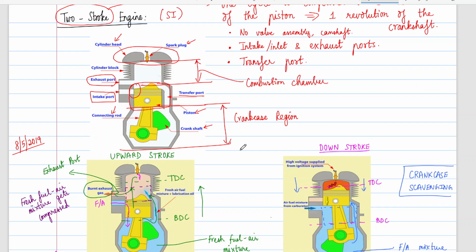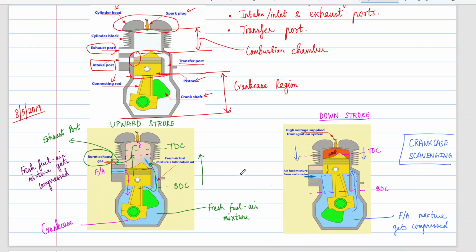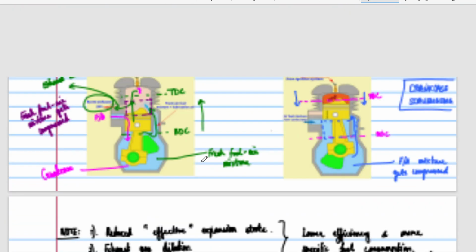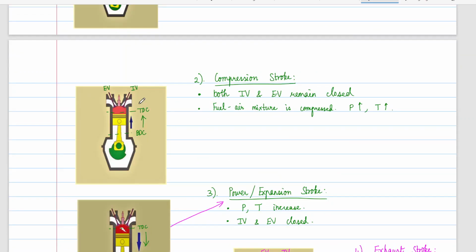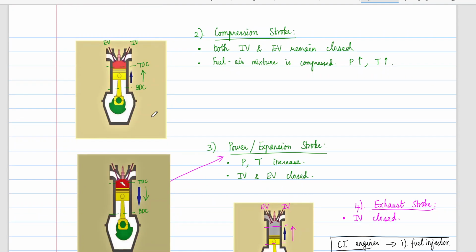are allowing you to directly, instead of sending in the fuel air mixture, as in the four-stroke engine here, where we are introducing the fuel air mixture, instead just introduce the air and directly inject the fuel. It can be diesel, or it can be petrol. So TGDI or TSI are generally the brand identities associated with this.